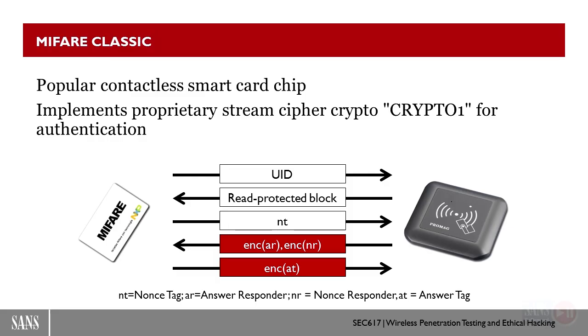So the unique ID, the UID for the card, is used to encrypt the data on the card, and then requires a secret key on the reader or within the application for the reader, which is the same as stored in the card. So we have the ability to do authentication on a couple of different components, the UID and those keys to decrypt the data. If we can't decrypt the data, it will tell us the read has failed. With MIFARE, they developed their own crypto standard.